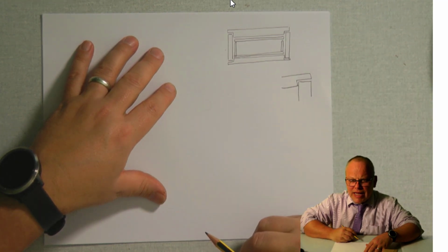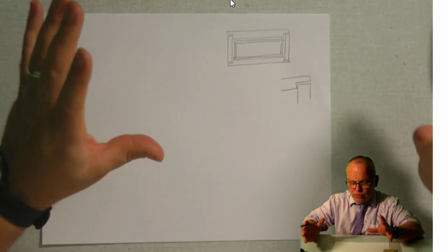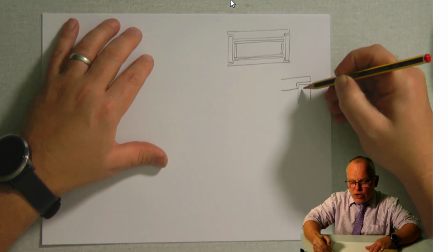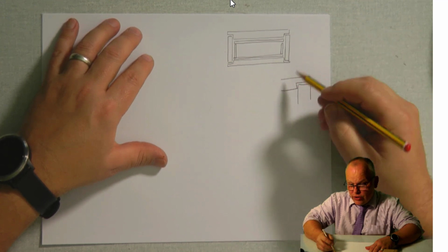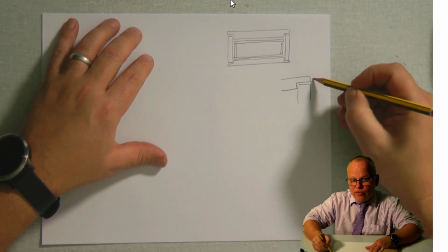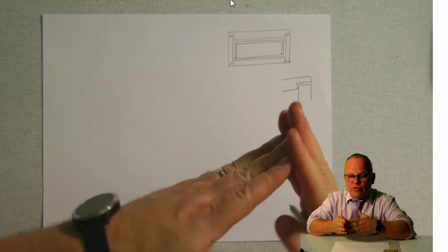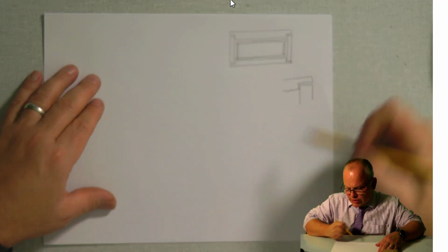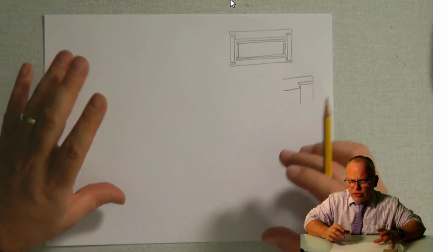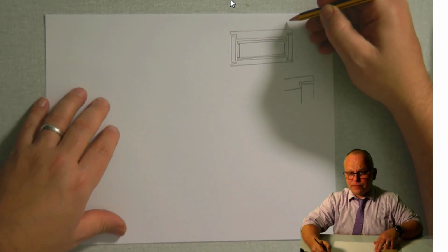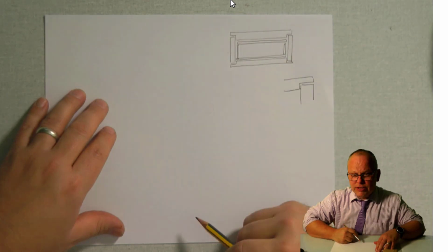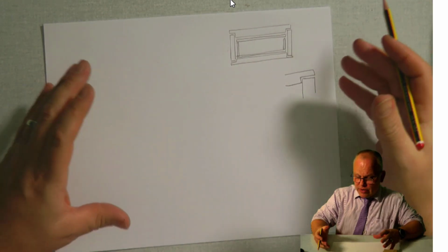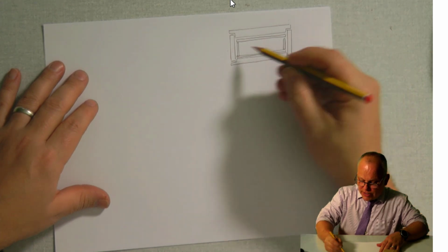Now, these are classic design and technology workshop joints. They're either pinned, or glued and screwed, or just glued. And the benefit, remember, of a wood joint is it keeps things from twisting and rotating. But this one doesn't offer huge amounts of strength. For what I'm doing, it's fine, and I might reinforce it with a screw, probably in a couple of points. PVA glue. So I'm showing my different parts.